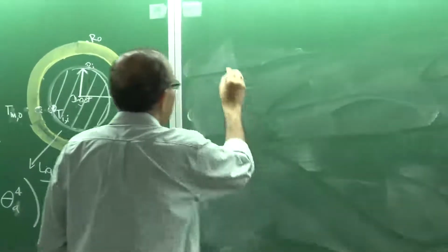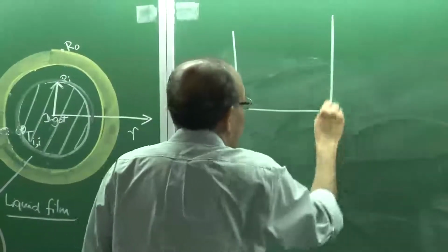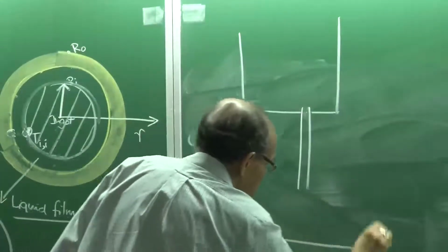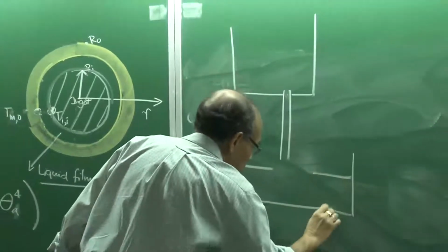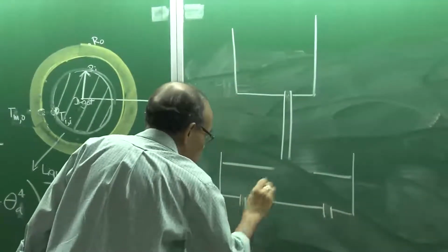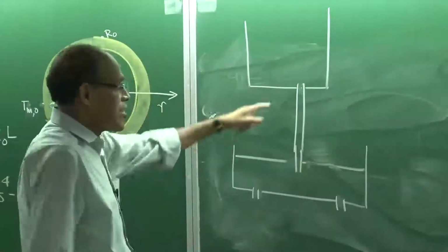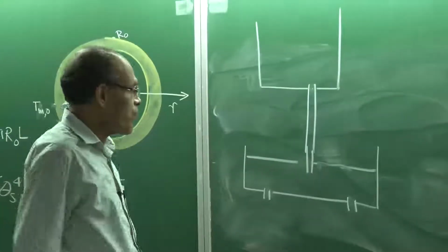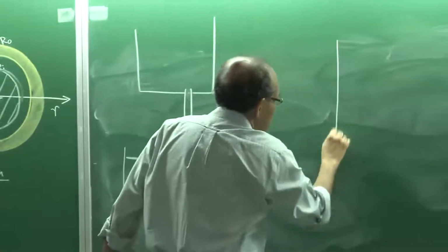If you remember, when I was talking about continuous casting, I talked about a ladle, a shroud and a tundish, where the molten steel gets transferred from one vessel to another. As I had also indicated, the shroud is like a ceramic tube.